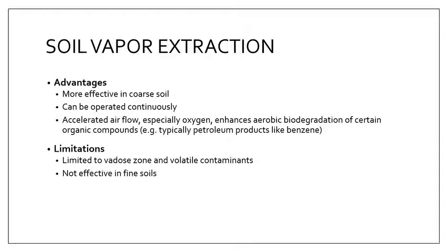Now, the advantage of soil vapor extraction is it's effective in coarse soil like sand and gravels, and this is mostly a machine-based method, so it can be done continuously. And the added benefit is you are increasing the airflow in the soil, meaning you get to introduce a lot of oxygen.